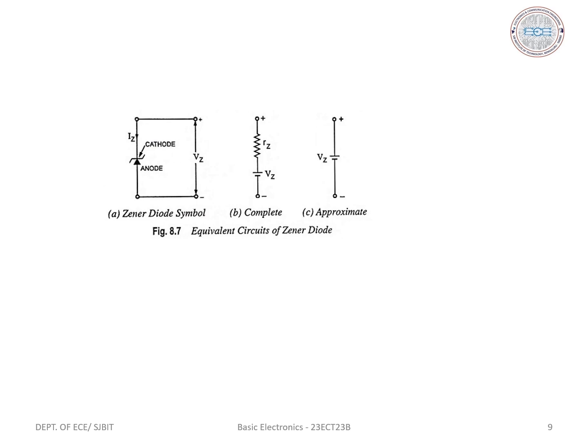Zener breakdown. Here the Zener breakdown is observed in Zener diodes having Vz less than 5 volts, or below 5 to 8 volts. Due to heavy doping in the Zener, the depletion region at the junction is very narrow. When the voltage across the junction is increased, the electric field across the depletion region becomes so high that the electrons are pulled out of the covalent bonds. This results in a sudden rise of current. This is known as Zener breakdown.